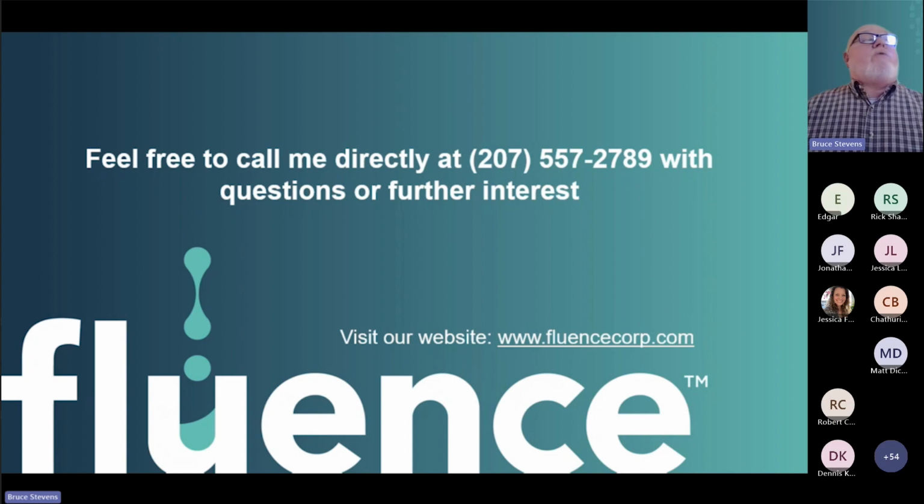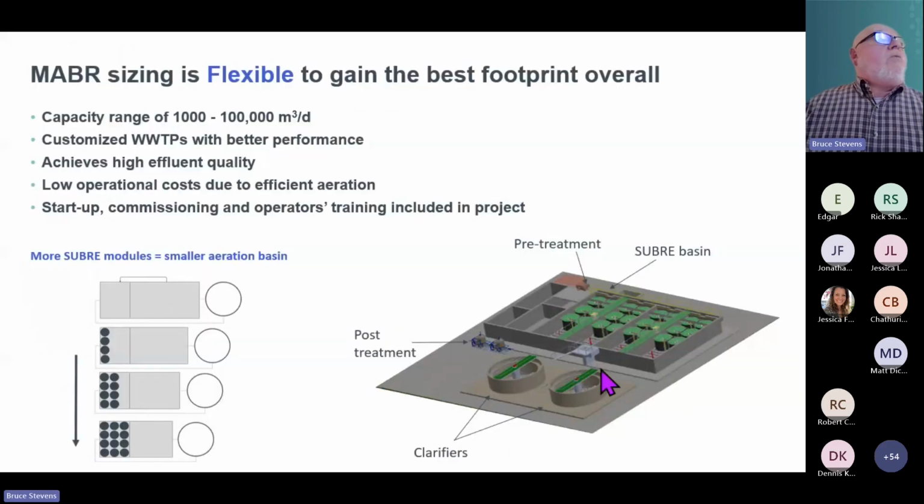There is no removal of the MABR towers. That's not part of our process requirement or design. Once the systems are fixed in place, they are attached to either the floor of the tankage or the wall. So the whole rack is set in there. Our experience in the last 10 years indicates there's no degradation of the membrane, the rack assembly, or the entire spiral. The biofilm is robust. It's very thin. It stays in that shape based on the feed, the forward flow, and the regular mixing that we put into the zone.